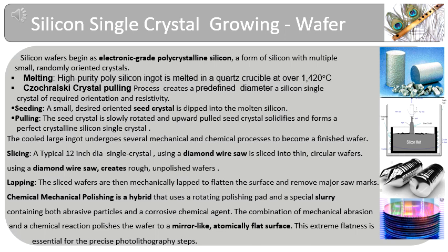Silicon single crystals are grown using the Czochralski method, in which a seed crystal is slowly pulled from molten silicon to form a cylindrical ingot. The ingot's diameter typically ranges between 100 mm to 300 mm, with crystal orientation like 100 or 111. Doping is introduced during growth: boron for p-type or phosphorus/arsenic for n-type, to control resistivity between 0.01 to 1000 ohm-centimeters. The ingot is then sliced into thin wafers using diamond wire saws, with thickness around 725 micrometers for 300 mm wafers. Rounding and grinding follow to improve mechanical strength and flatness.